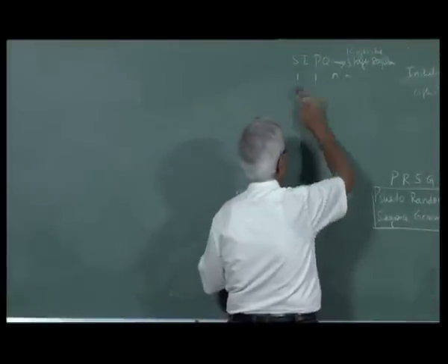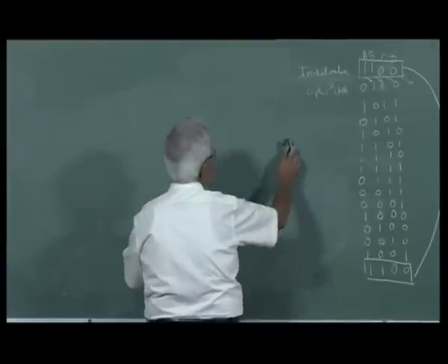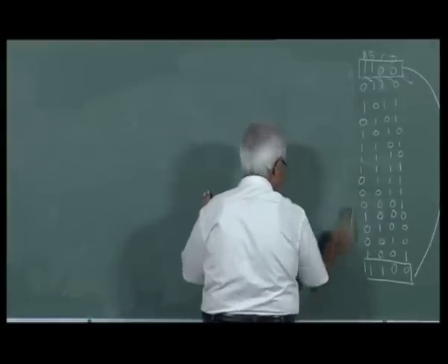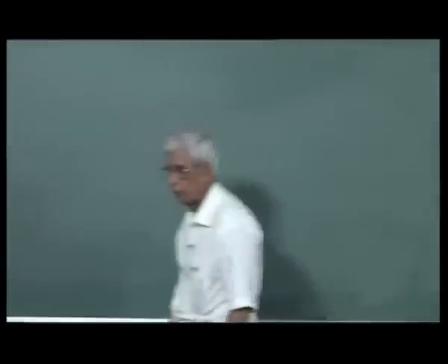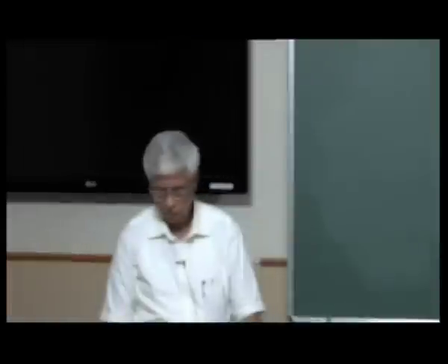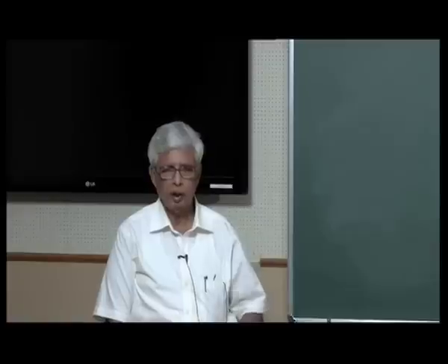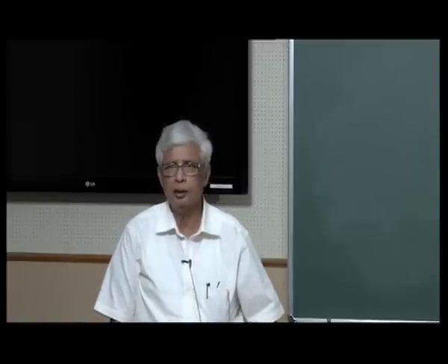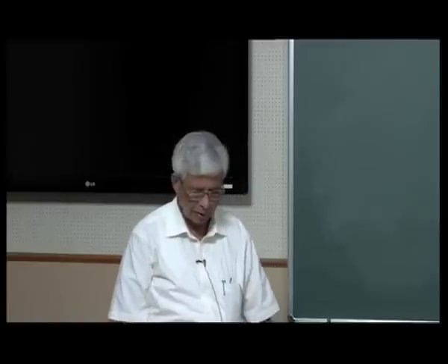We will see, for example, if you have an elevator, how does it work? How do you design it? What are the various states in the elevator, how does it go from one state to the next, and how do you define and design it? Like that there are other applications. Supposing you have an input pattern and require a particular output sequence, how do you define it? So these are general sequential circuit designs.